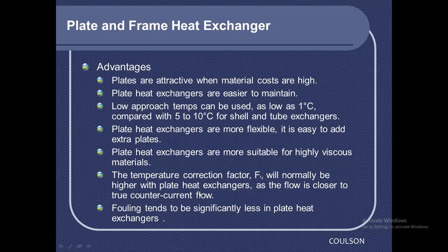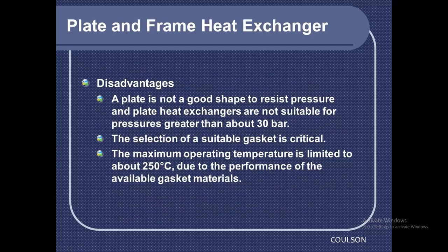However, for this type of heat exchanger, you have to use only clean fluids. Clean, and also aside from that, it can also handle highly viscous fluids. You can see it in here. So please take note of the special applications of each of the different types of heat exchangers. So for this one, it's really critical. I mentioned also at the beginning that the gasket that should be chosen is well adapted to the feed that is going to be processed.